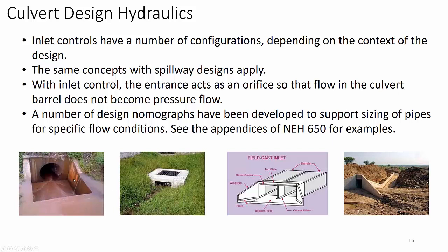We'll talk about those in a moment. The same we can do in this particular bioswale, where we have water flowing through this vegetative system, and the vegetation captures much of the silt. You can see a flow line here where it's broken through, and then water drops over this crest into a box drop inlet. So we have multiple control systems here. Water controlled flowing into the vegetative channel, water flowing through the vegetative channel, then water flowing through this inlet. And all of those are design elements.